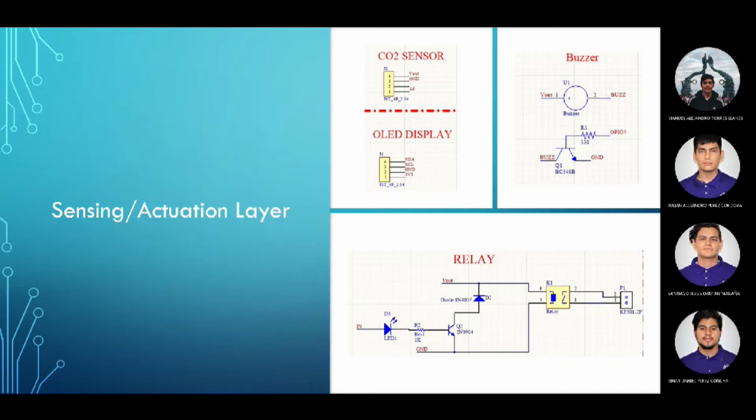We also have a relay connected to our ESP32, and when that signal is sent through by passing that 1000 ppm limit, it will activate the relay, and this is connected through a motor. It could be air conditioning, it could be an opening window system, and all of that is used to regulate the ppm inside a given room.